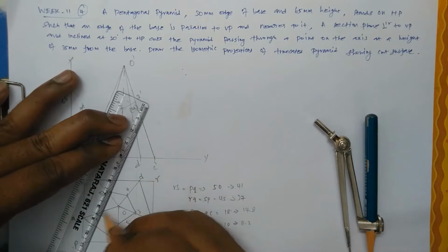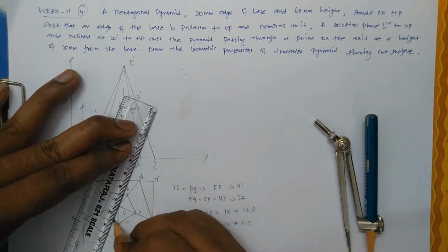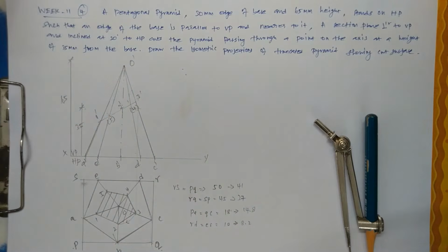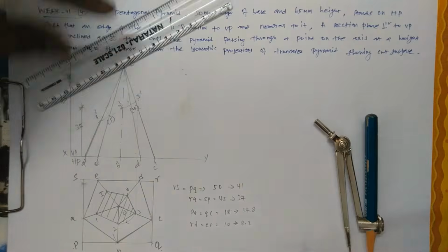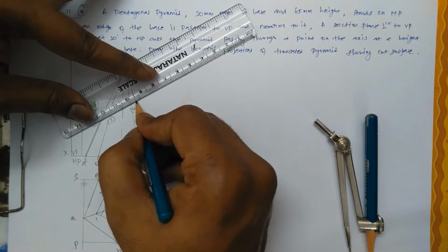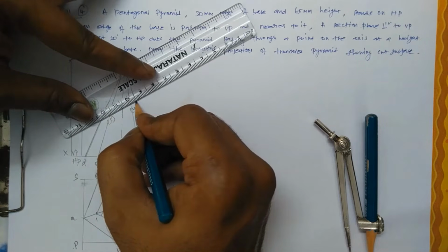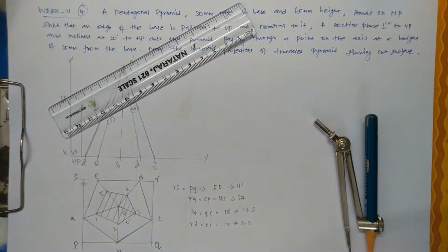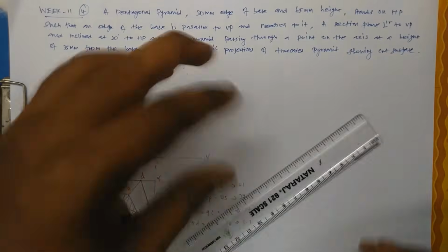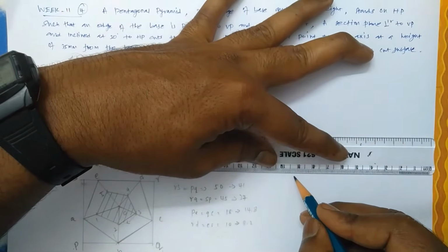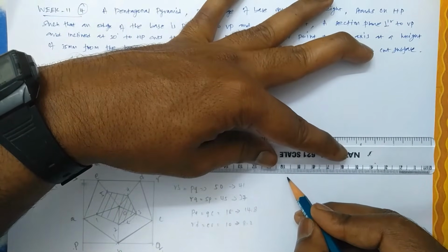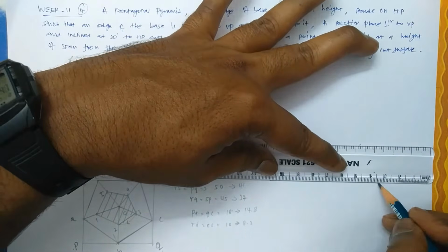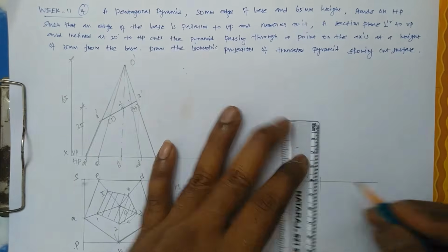Hatch the portion, this is only what you will see from the top. It's the top view of the sectioned or truncated pyramid. So next let us keep this same in the isometric plane. The height 3 is more, so let us keep that edge at the corner toward the observer, with the cut surface towards the observer.